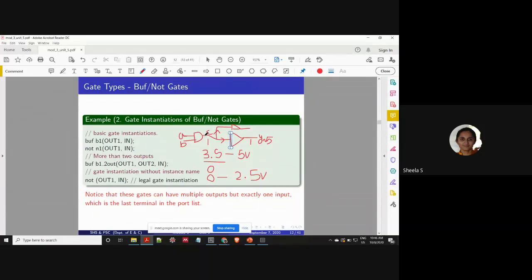Even though the voltage between the output terminal and ground remains constant, the current flowing from the output terminal will be divided into two paths. And we know that voltage is equal to current times the resistance present in the wire. So if the strength of this is less, then it cannot drive more gates properly.